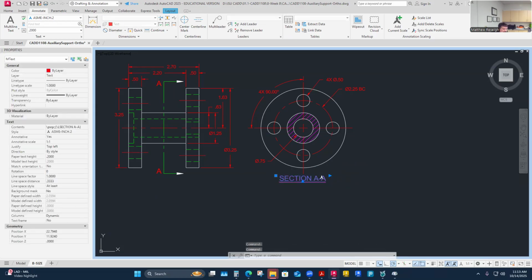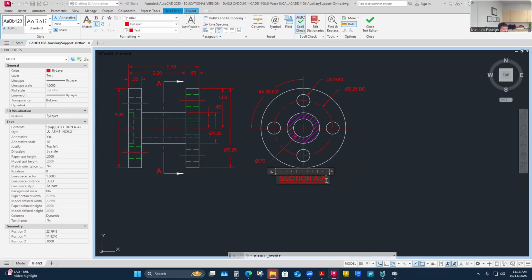because it's pretty common that this isn't usually all that a view will carry. Sometimes there'll be a second line, and the second line and the other data that might go with this would be back to the regular text size, just so you know. Sometimes it'll carry the scale. I can actually take this view in that viewport and scale it differently than where the cutting plane was done.